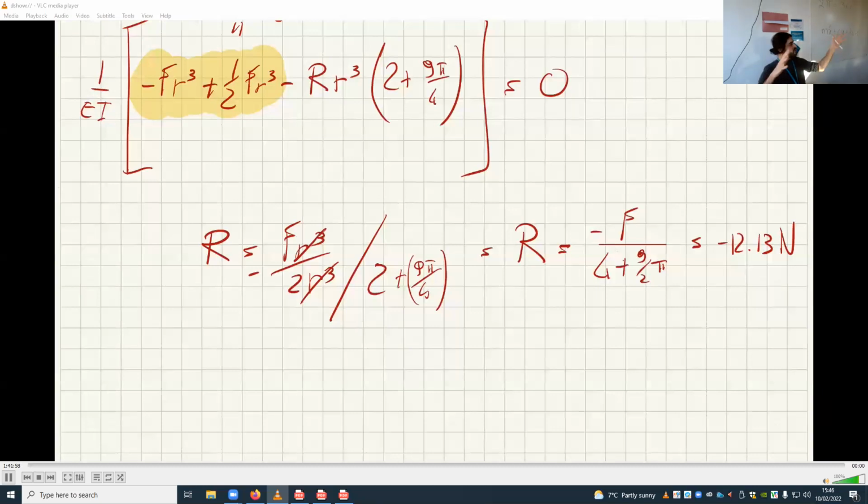When you do the velocity diagrams or acceleration diagrams of a mechanism, you're looking at that specific instant of time. At the next instant of time, that's changing. So in order to find the span of the entire mechanism while it's moving, you need to integrate over the 360 degrees angle, say, of the crank.